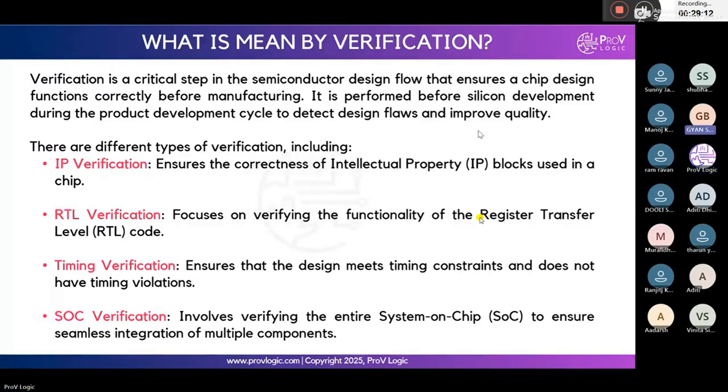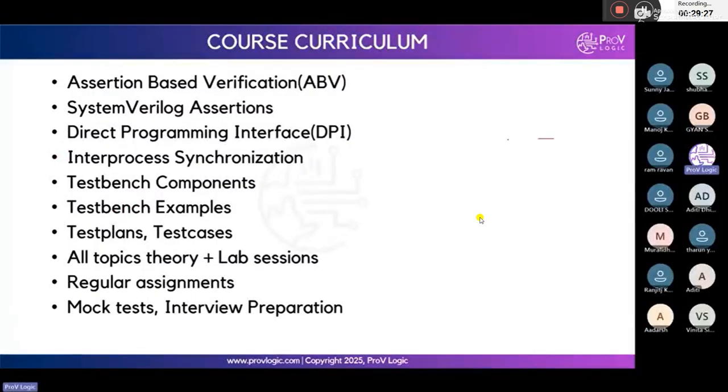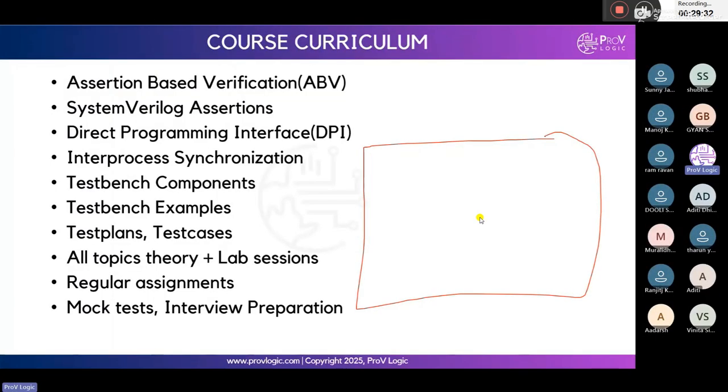Okay, so is there any change in the process? Let's say we write a test bench for a particular design. The only difference is the silicon, right? The actual hardware we get. In pre-silicon, I told you about the debug units. In post-silicon, mostly we work under DFD, which means designed for debug. The DFD team has separate hardware, because I told you we connect the debug units using the cross trigger network.